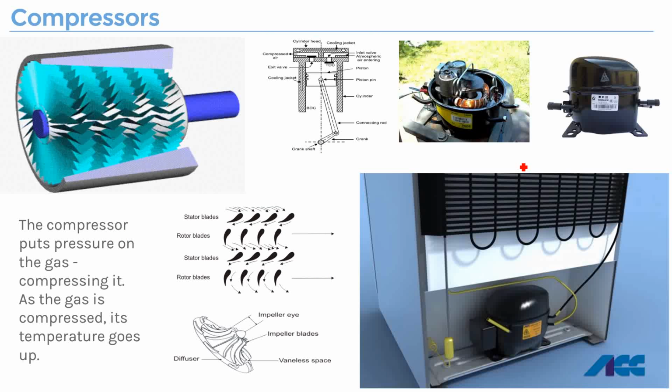So now we could look at all these components one by one. The compressor is just a mechanical device, so not really related to what we're introducing in this course. You just need to know that the function of the compressor in this refrigeration cycle is to compress the gas. We know from the evaporator we have this refrigerant vapor. The gas is more compressible and can be compressed to high pressure and high temperature. That's the function of the compressor in this refrigeration cycle.